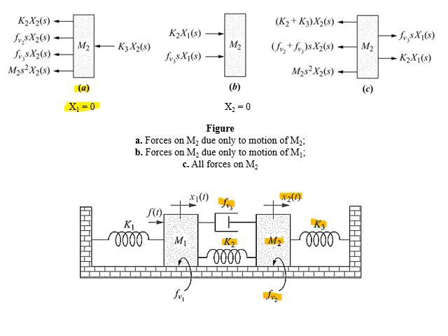The spring with coefficient K3 applies an opposing force. The surface friction represented by rho v2 applies an opposing force. Both the spring and damper common between M1 and M2 apply an opposing force on M2. The mass of M2 also applies an opposing force on M2.